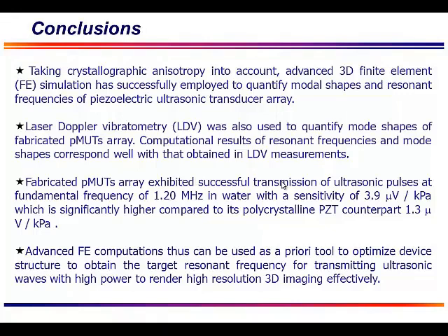With the experimental findings, we found that the sensitivity of our device was 3.9 microvolt per kilopascal, and with the polycrystalline ceramic part it was 1.3. So it is a huge, significant improvement of our device. Finally, finite element simulation can be a great tool for optimizing the pMUT device. Thank you for your attention.